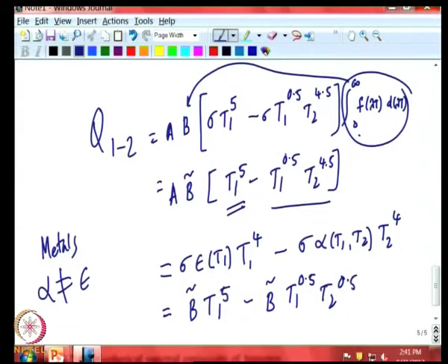So, these two results are the same really, but derived in two different ways, and it clearly tells you that the traditional assumption that emissive power goes as the 4th power of T is only true for a black body. If the bodies are not black and not gray, then you can have emissive power having powers larger than 4 or even less, depending on how the emissivity and absorptivity of that surface depends on wavelength.